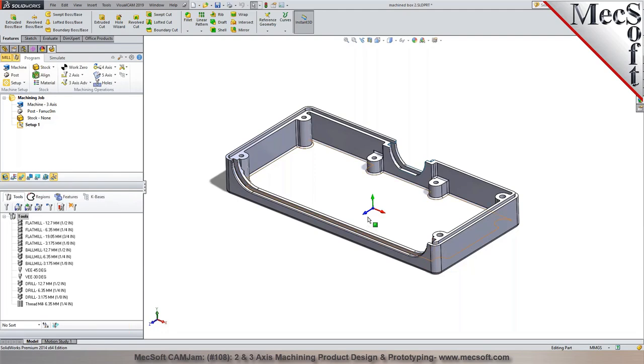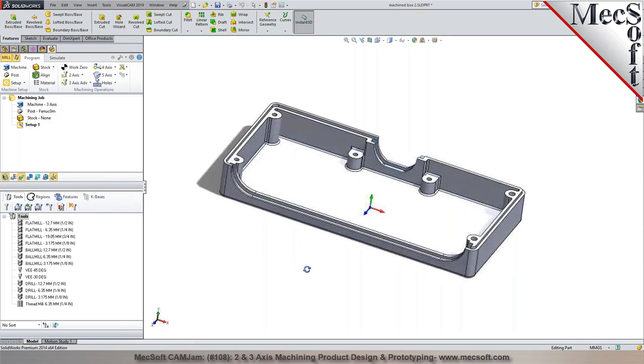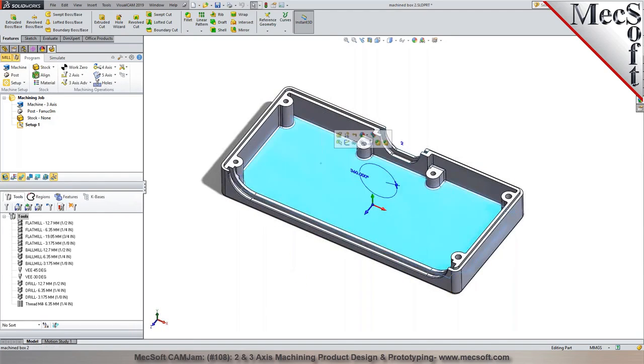So the blue arrow represents your Z-axis, the red arrow represents your X, and the green arrow represents the Y-axis. So if you take a look at it normal to this view, your Z-axis is normal to this particular face, what I've highlighted in here, which means that's your cutting direction. But based on the way the part is designed or modeled, it looks like you'd want to basically pocket out these features. So you want to put the Z perpendicular or normal to this face. Am I correct? Yes. Okay.